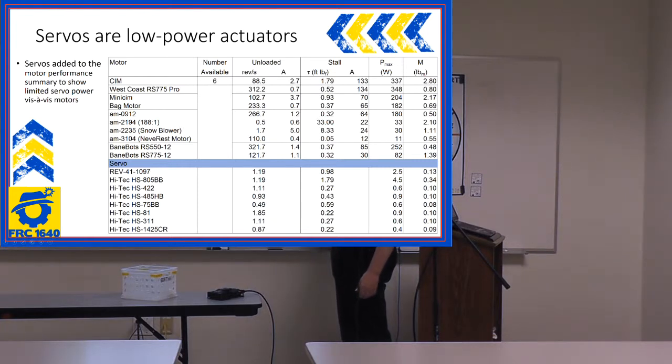This is the maximum power in watts, and with our motors, these 2 are almost 350 watts. That's a lot of power. And 204, 180, 180, here's 250. My weakest motor is 11 watts. That's the FTC motor. We don't use that on our robot, because why would I use an 11-watt motor when I can use a 300-watt motor?